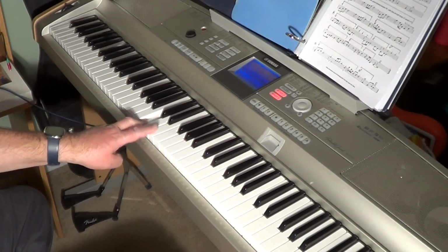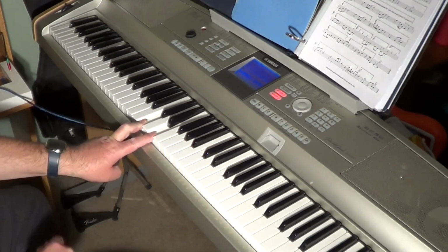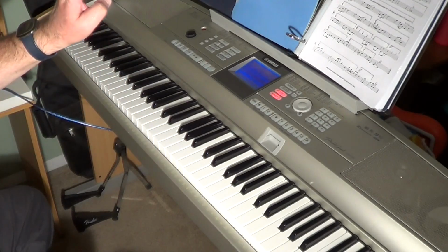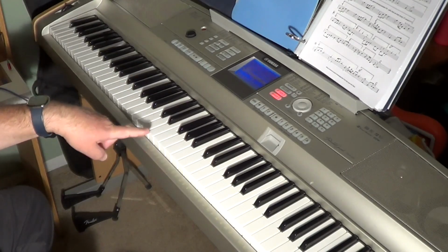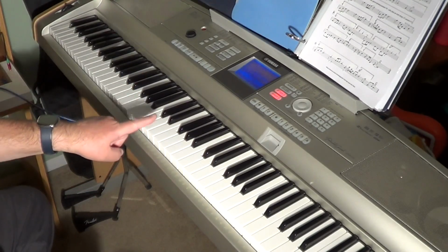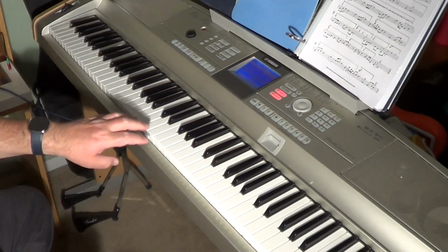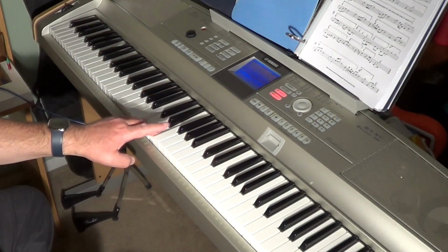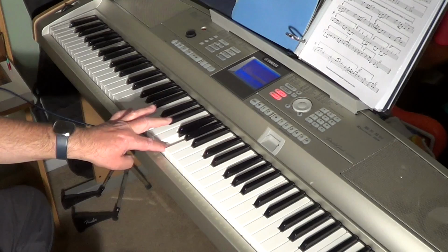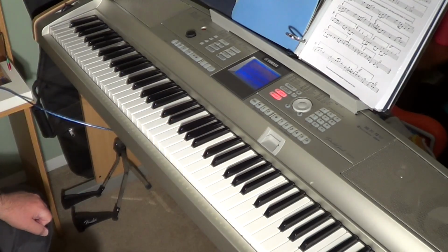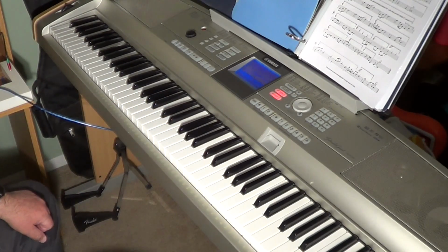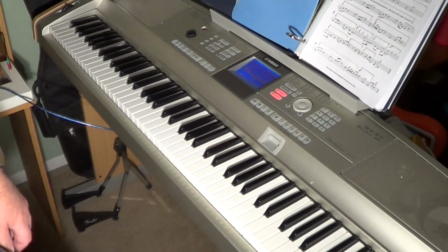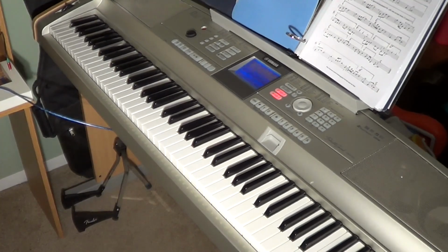Finally, we can try to see if the trigger is generated when two keys are pressed and we release the one with a lower pitch. In fact, with this configuration, only if the trigger is generated when releasing the key, we will be able to hear the other note. Here it goes. And yes, it works too, perfectly blending with the priority on low feature.